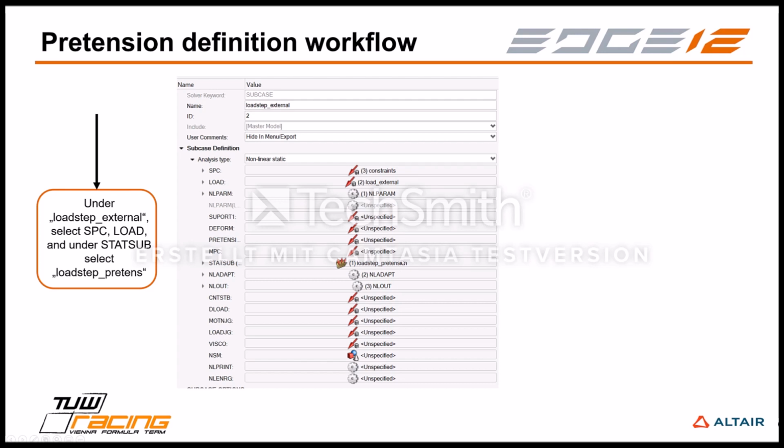So when the solver solves our model, the pretension load step gets solved first, and the results from this load step will be then used as a starting point of our second load step. So this will take our pretension into account, and then we'll apply the loads externally.